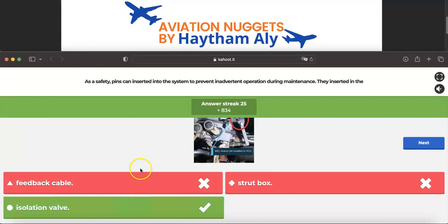Thrust reverser deactivation for maintenance: you always close the isolation valve by the deactivation lever, and you need to insert the pins to prevent the hydraulic from going to the hydraulic actuator of the thrust reverser system.